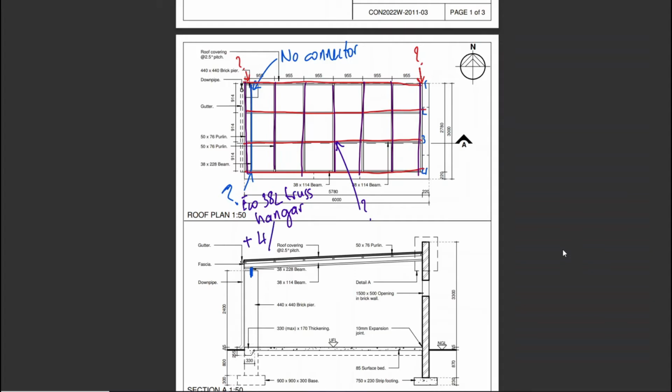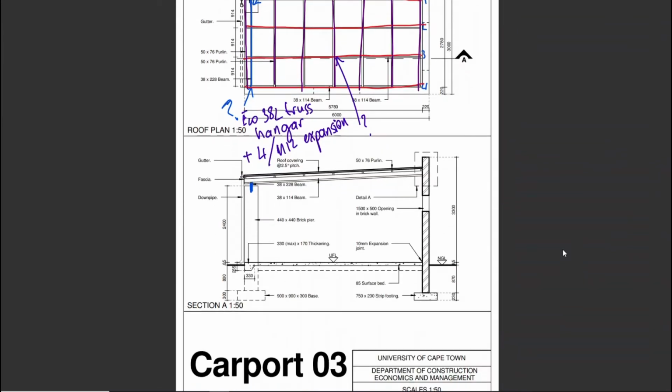And it comes with 4 M12 expansion bolts. And expansion bolts are pretty awesome, I'll be honest. I absolutely love them. Once you've drilled your hole into the brickwork, you put your bolt in, and as you tighten that bolt, it's going to start applying pressure outwards.